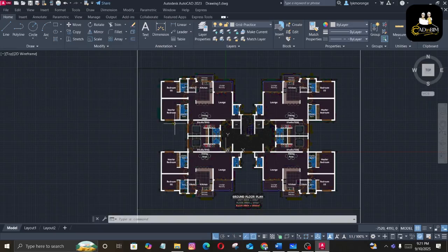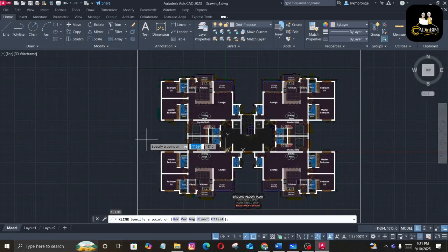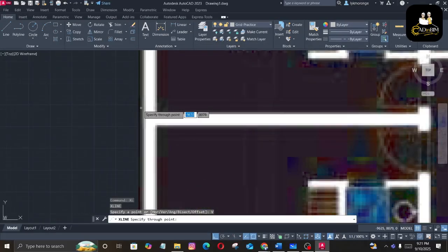So ensure that you have imported, and you want us to be at the same level so that once we start drawing the grids, we are all together. But there is one thing I want to add on the grid. As you can see, if I come to my screen and write XL, enter, then V, despite me giving my grid line as a center, I can't see those lines here. I can't really tell whether these are center lines.